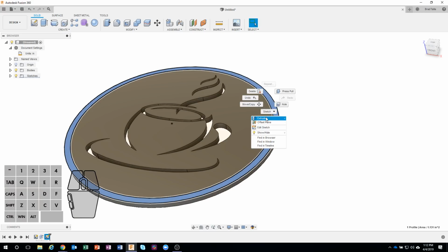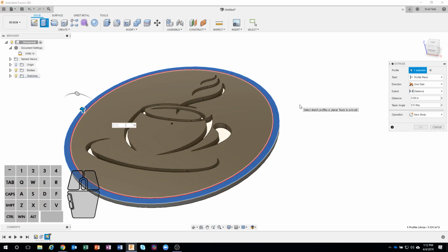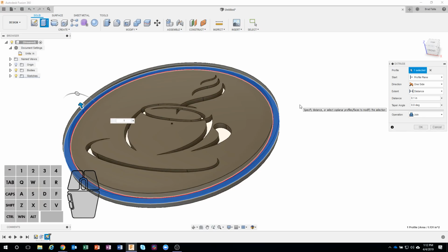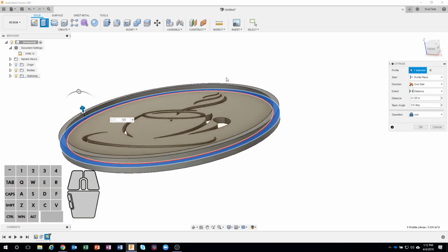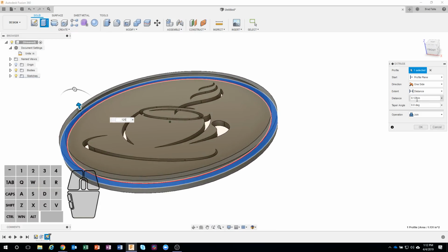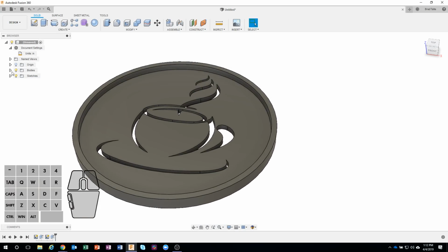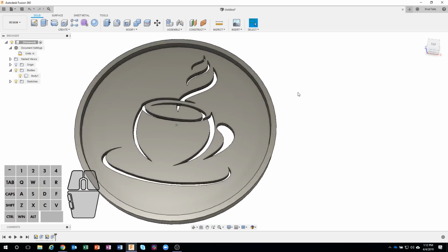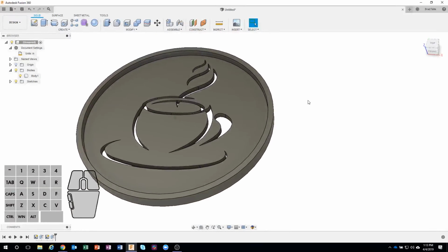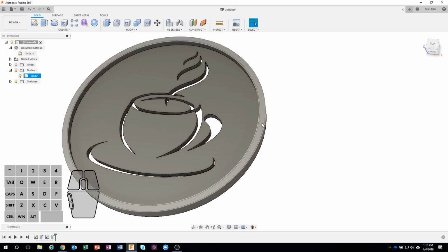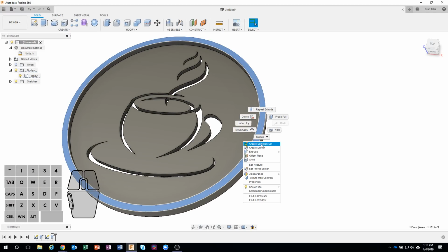and let's go ahead and extrude that up 0.1 inches. Actually, let's go maybe 0.125 in this case. Let's just give it a little bit more of a height. So we're going up 0.125, it's joining. So we still have just one body in this case. And then the last thing I want to do is to create that little handle. So maybe I'll just start on this top face and create a sketch.